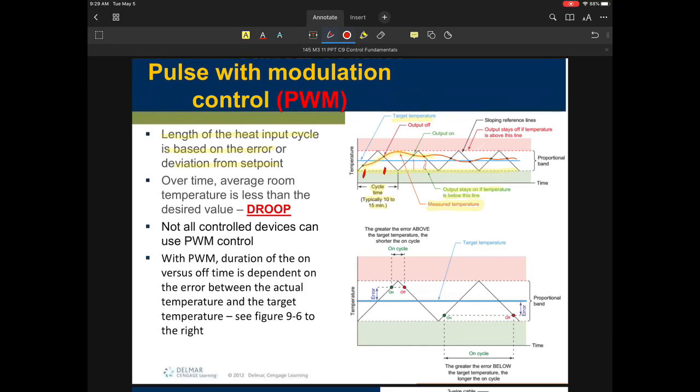And the challenge in PWM control is being able to diagnose this signal, recognizing whether it should be on or shouldn't be running. So sometimes you might have to provide a much greater error to see what the signal is doing. Is it turning on or off? And then you might have to change the proportional band. If it's not advancing fast enough, you might have to manipulate the proportional band, hopefully without it hunting. And that's the one thing you have to deal with in there.